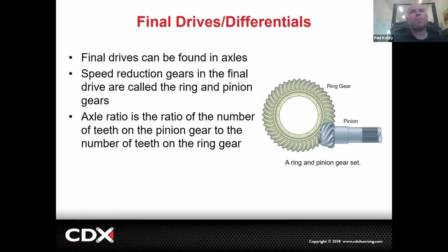And when it does that wiping action, there's some pretty specific requirements for the oil on there. So when you go to service a differential, a lot of times it's calling for a hypoid gear oil. If you look in the fine print on the bottle, it will. It may be GL4, GL5, or 80W-90, or even 90W-140 or something, but a lot of times it'll say hypoid because we really have some specific lubrication requirements due to that design.